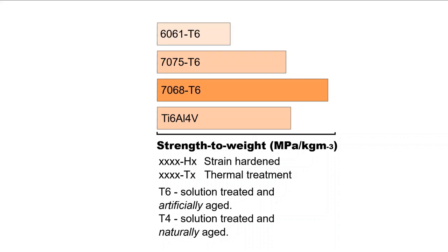There are a wide range of these types of treatments to deliver a temper, such that if conditions are optimal, you can end up with an aluminium alloy exceeding the specific strength of even titanium. There are many T designations for alloys. During this lecture, we'll look at the most prominent, T6, which specifies artificial aging, and by way of doing so, also cover natural aging.